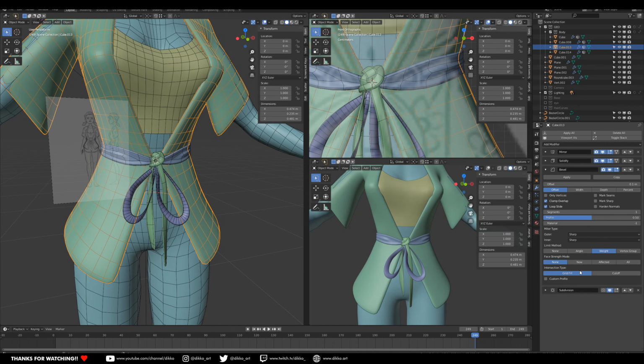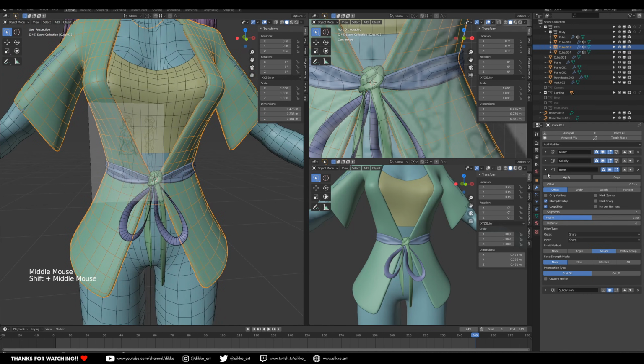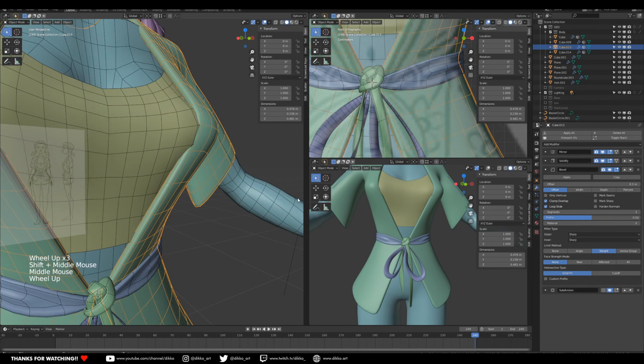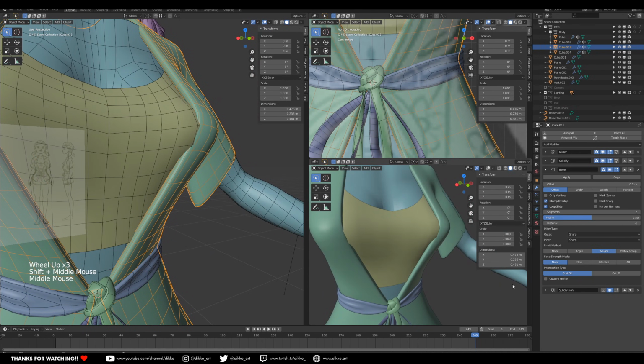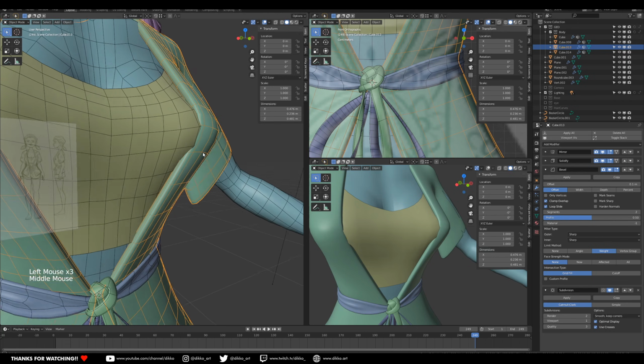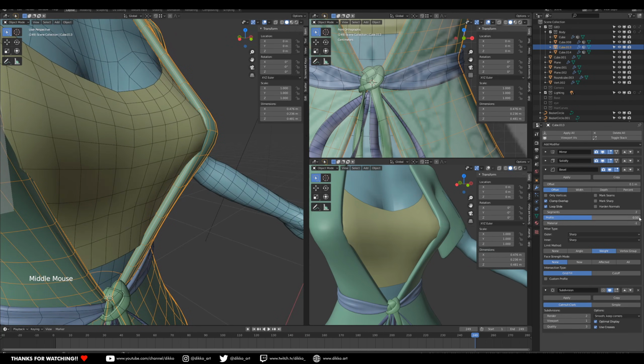And in this case, I'm placing my bevel modifier before my subdivision, but after the solidify modifier. So the solidify modifier will calculate first, then the bevel modifier, and then the subdivision. So that way I'll get those sharp corners on both the inside and the outside of the kimono. And then the subdivision surface will just smooth that out a little bit. So I'm effectively mitigating the amount of performance hit I get from my modeling techniques, because the subdivision modifier is probably one of the most resource intensive modifiers in Blender.